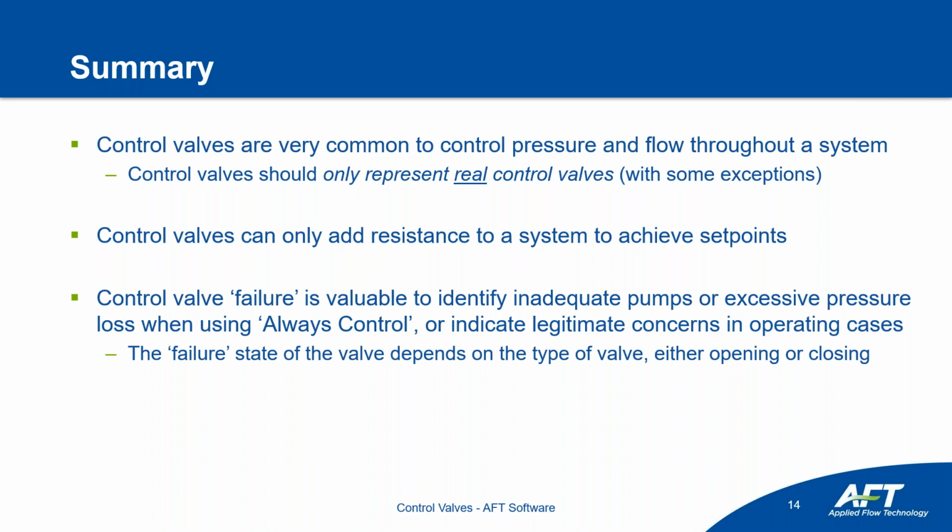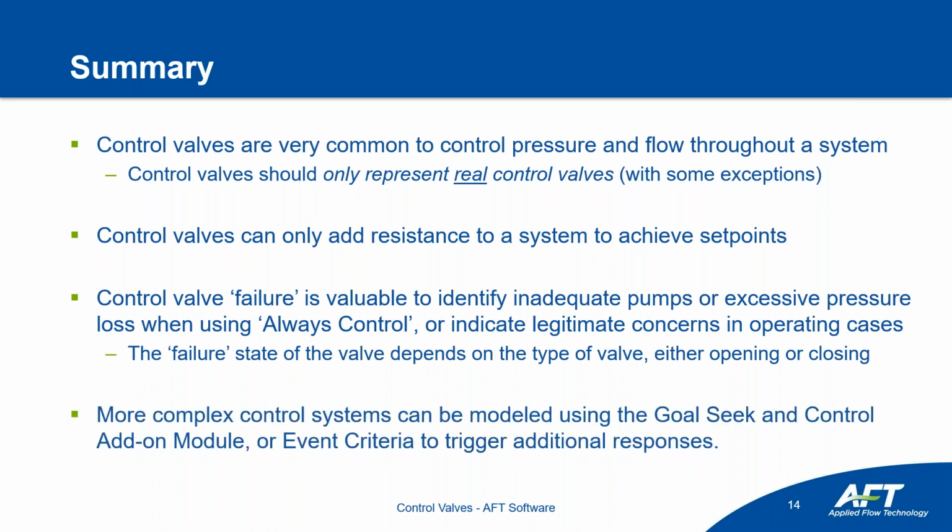As we talked about, we use failure as the terminology for unable to achieve set point, and that failure state depends on the valve itself, whether it's flow control, pressure reducing, pressure sustaining, or that constant pressure loss control valve. Then finally, as we touched on briefly, if you do have more complex control systems, you can check out the goal seek and control module or using event criteria.